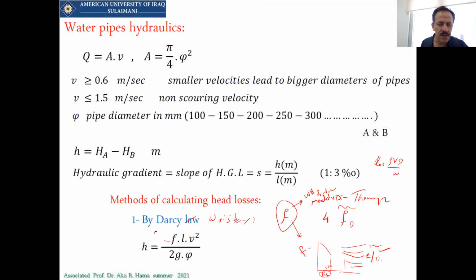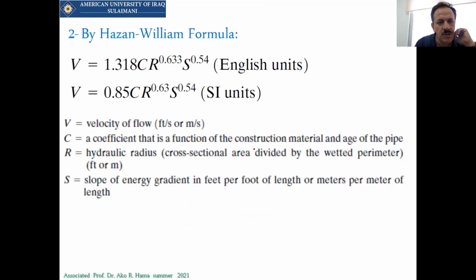So this is called the Darcy-Weisbach equation, and it will be equal to 4 times the other friction factor, which is no longer used in fluids. It's only the well-known one, which is the Darcy-Weisbach. Now we say that we can use this equation, or we can use the Hazen-Williams equation, for finding the head loss. What I should do with that head loss is use it for finding the head at point B.